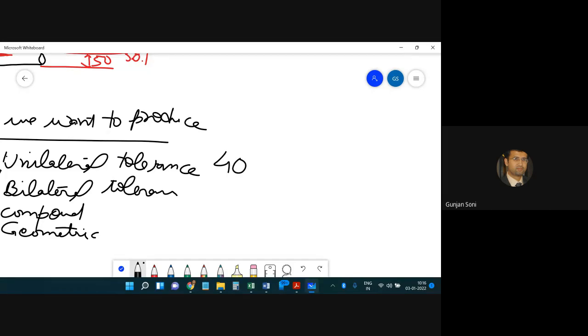40, if it's the basic size. And in the superscript we indicate the tolerance over here. So the limits are indicated as superscript over here. You can see that they are all going in the positive direction. Okay, so you may be getting 40.01, 40.0. So these are the limits between which you will be getting your dimensions.